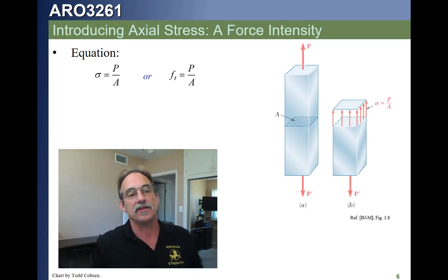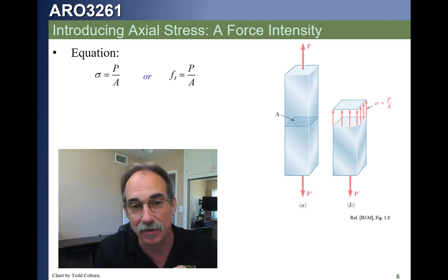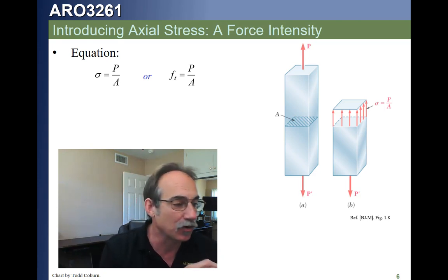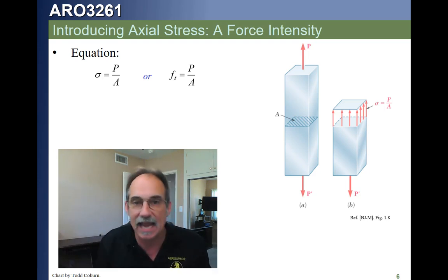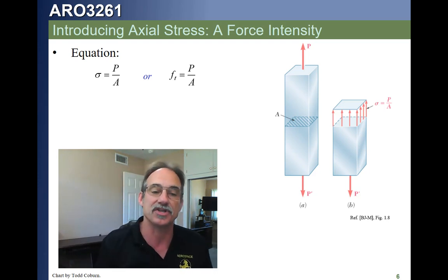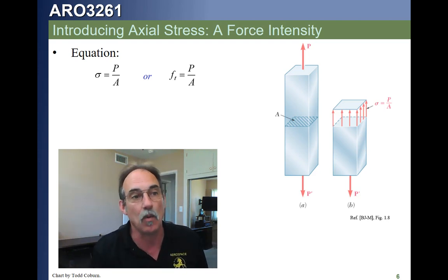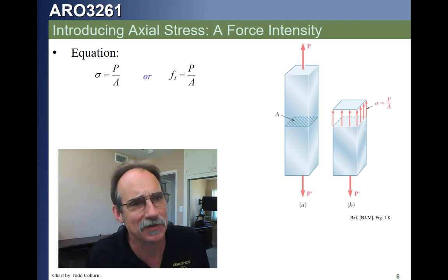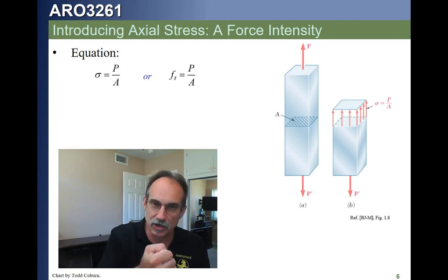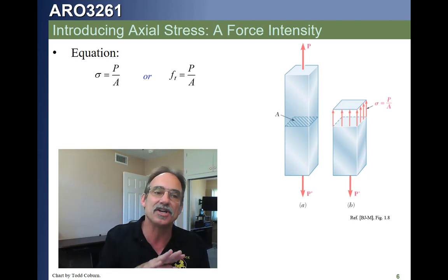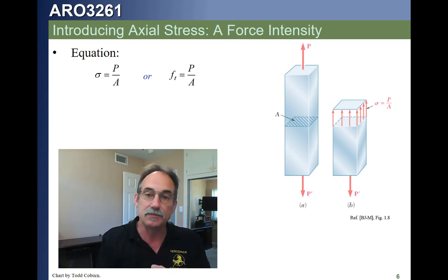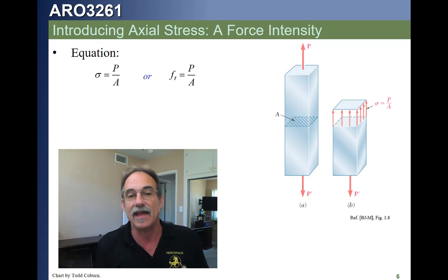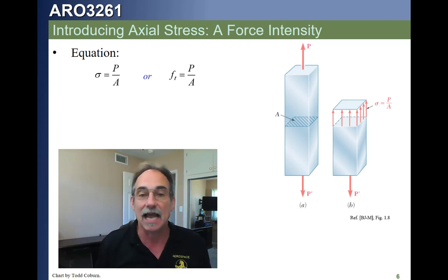Now we're going to find out that the stress just doesn't magically distribute itself evenly. It's like having a group of 5 friends that all are hugging each other, and you grab onto the arm of one of them and yank on him. The force on that person is pretty direct. The force on the others is a function of where they're distributed. In the same way, since structures are people too, if you pull on a structural member, the force doesn't magically even itself out throughout the section. It takes space and distance to do that, and that gets to a more complicated type of analysis.